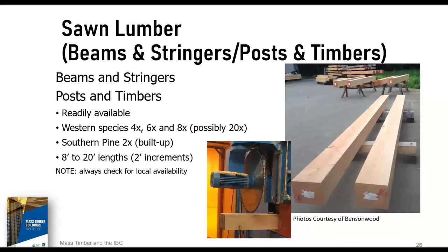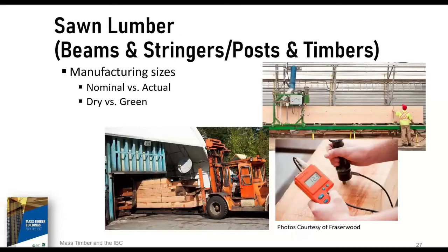As you can see, for the different sizes, some of the western species, the sizes that are out there go all the way up to 20 by. Southern pine is typically going to be built up, and the lengths can be provided to you in 8 to 20 foot lengths, typically in 2 foot increments.